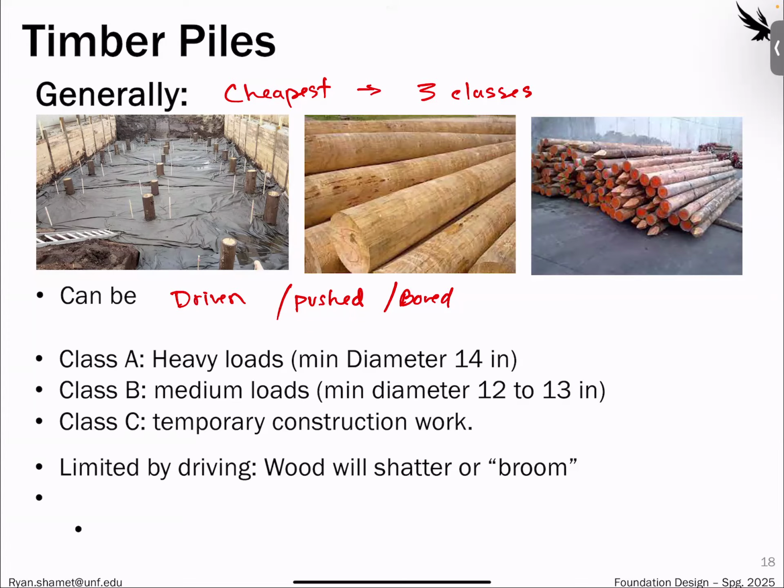The benefit of timber piles is that if you use native wood, if you're using cypress or something that's used to being in that area, then it's not going to degrade. So these piles were underwater for like 50, 60, 80 years, and they were still perfectly fine, so they were kind of a pain to get up. So that's one of the benefits of it. Obviously, though, it's limited by driving because the wood will shatter or broom.